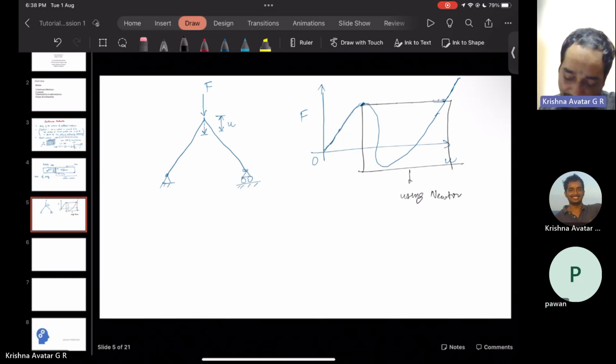So we use a technique called the arc length approach. In that case, we have both the increment in force and the increment in displacement as unknowns. Up to this point, the method works as if we are using Newton-Raphson, and then it changes the displacement so that we start following this curve, and that it does automatically. You don't need to do anything; that's inbuilt in the algorithm. It follows back and gives us the entire displacement history with respect to load.